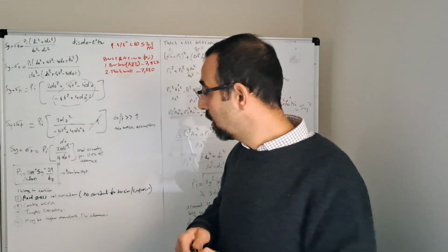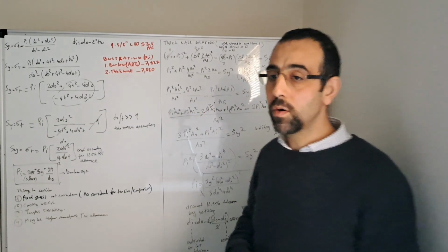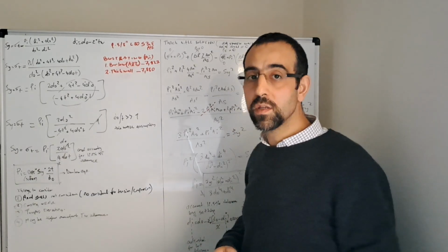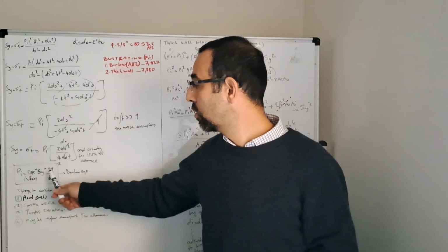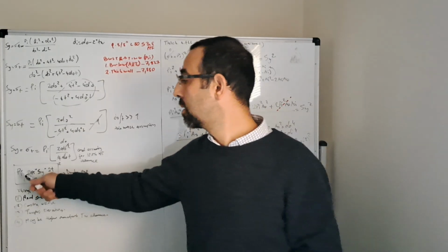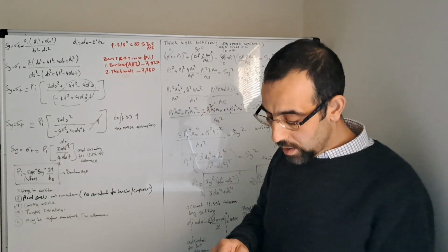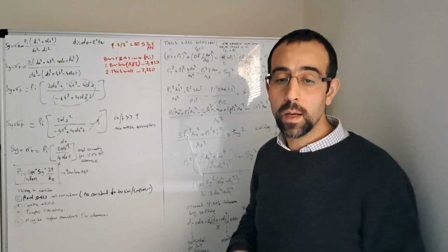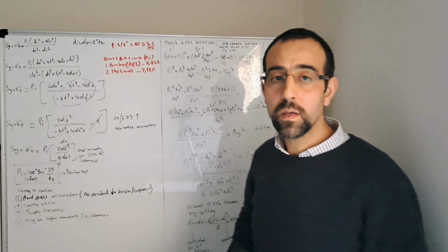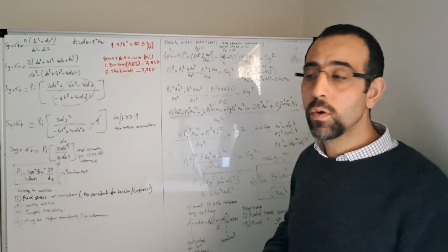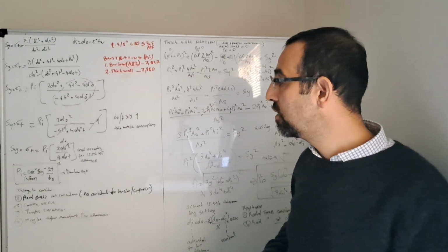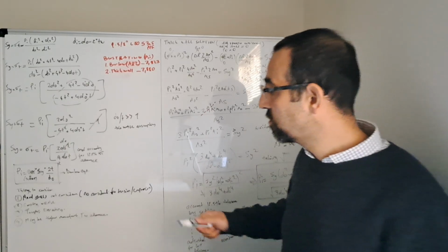So for wall thickness, depending on the vendor, between the operator and the vendor, depending on the order, depending on the specifications, maybe you could specify a tighter tolerance on the wall thickness, and that will give you a higher burst pressure. You can even request some specimen test to validate the wall thickness or increase the wall thickness or reduce the wall thickness tolerance.